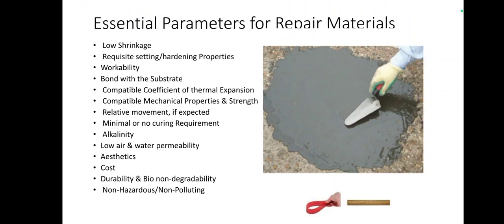Mostly you might have seen this in concrete roads. If a new road is laid with concrete, it looks very pleasant. Suppose for placing cables they dig and break the concrete, altering the concrete, then place the cable and once again cover it with some new concrete. That new concrete may not have the same properties as the old concrete.